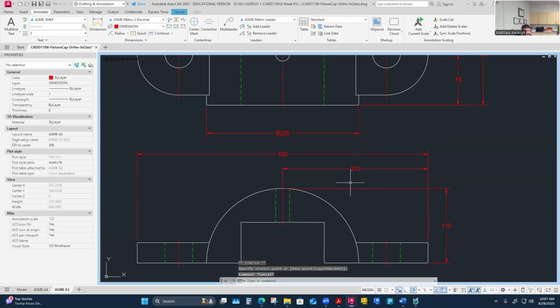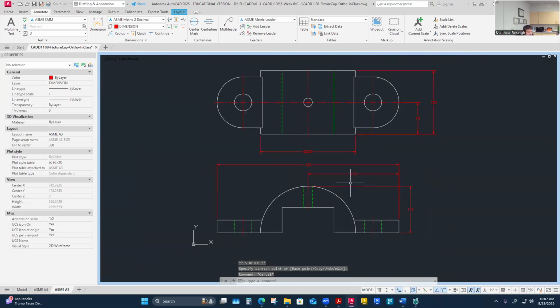We'll see that in a minute, but I'm going to move on from the cylindrical shape, or maybe I'll stay with it and say, well, it's got that slot feature inside. Where should I dimension the slot feature? I don't want to dimension it hidden in the top view. Anything associated with its size, it's a rectangular type of feature, so it should have a length and width, or in this case, a width and height. So let's do the width and height of this slot as its size.